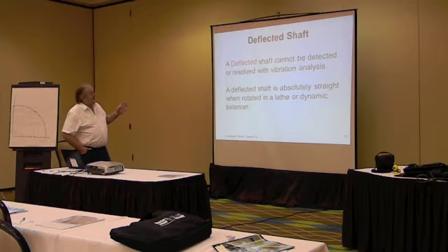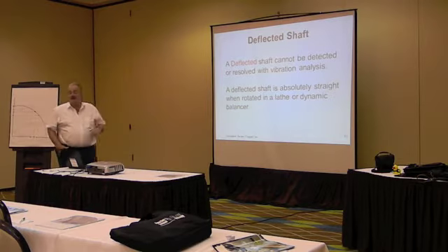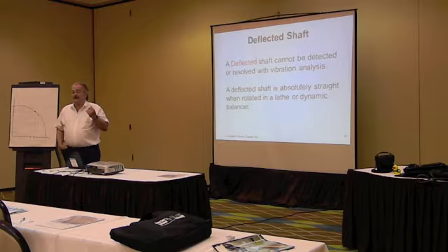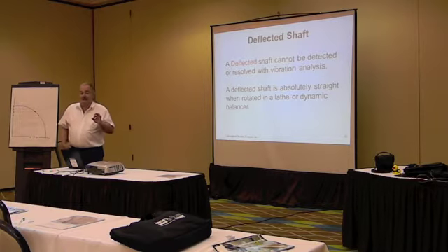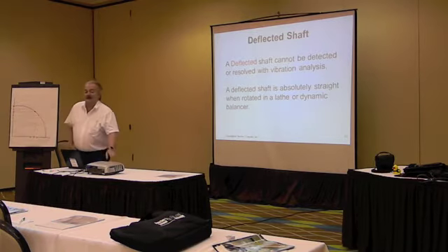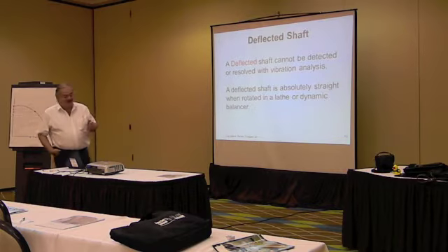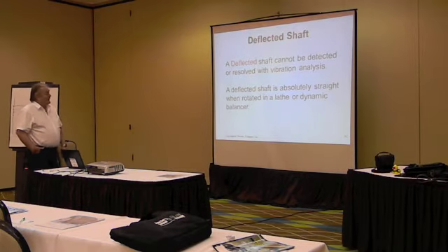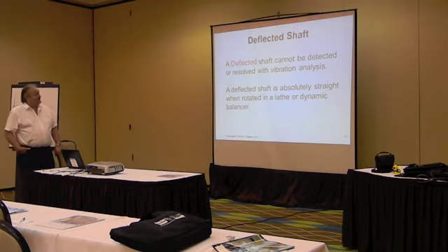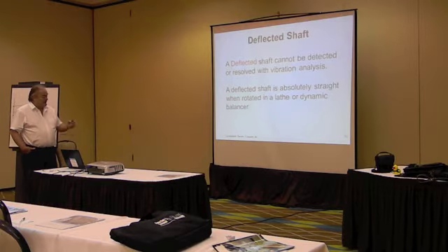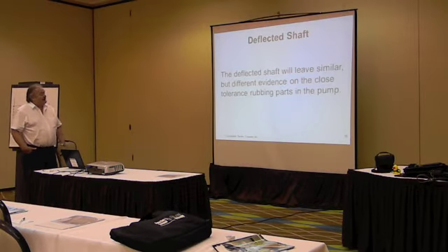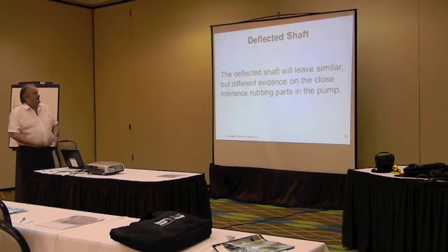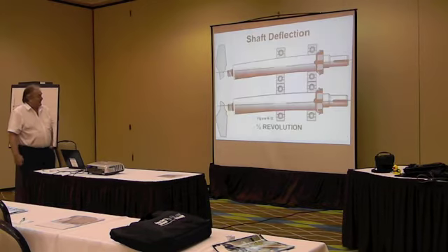A deflected shaft cannot be detected or resolved in vibration analysis. What the vibration analysis might detect is if the deflected shaft is leading to pump parts bumping and scraping, that will be on the vibration analysis. But the vibration analysis in itself cannot detect the deflected shaft, because a deflected shaft is absolutely straight when it's rotated in a linear dynamic balancer. The deflected shaft will leave similar but different evidence on the close tolerance rubbing parts inside of the pump.